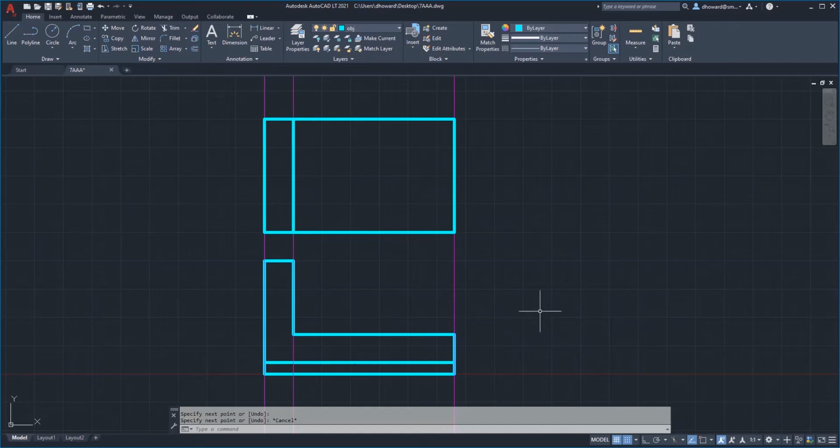And that's it for the object lines, again, without doing the holes and the arc. There is a hidden line for this lip that goes underneath, and that appears to go right down the middle, pretty close.